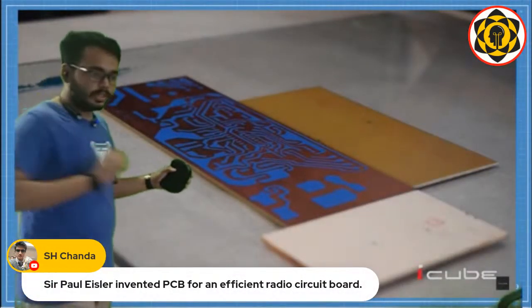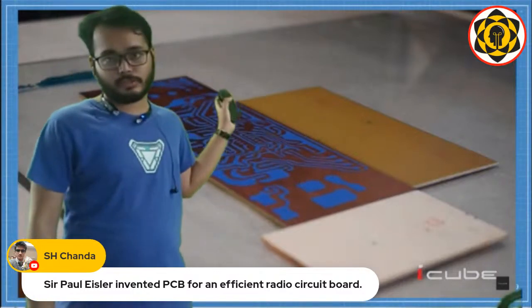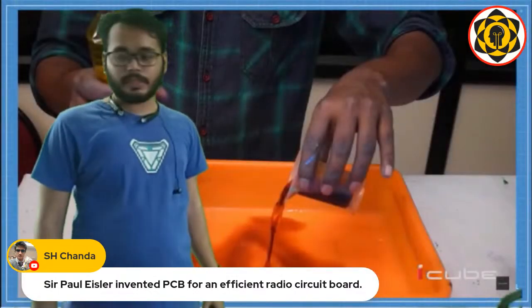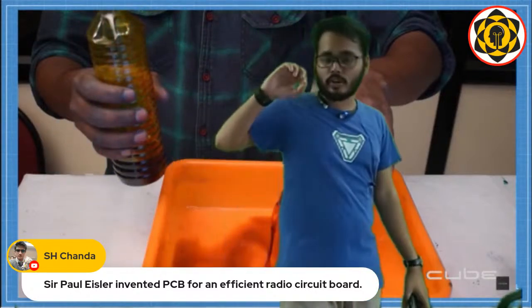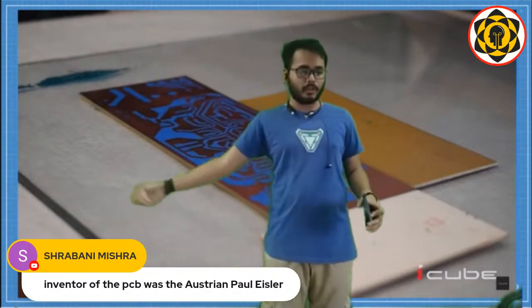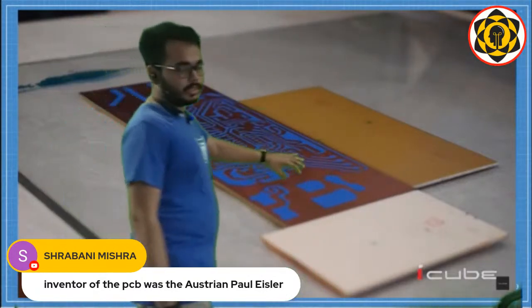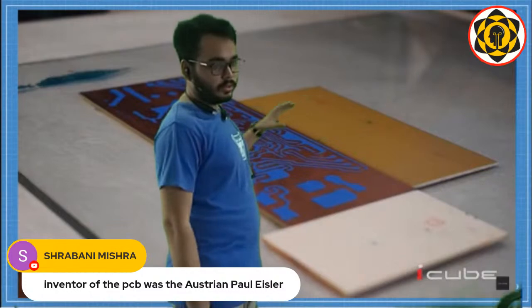Now, as you can see, with a swipe of a hand, this thing is ready. The blue paint is everywhere that you want the circuits to be. The traces have been marked. So now let's begin the next step, that is etching. Since we have marked the places where we want the copper to be, we have to get the copper off of the other places, right? As you can see, the copper is on the whole plate, because it's a total copper plate, and we want the copper to be in these blue areas. So the other places which have copper but no paint need to go.